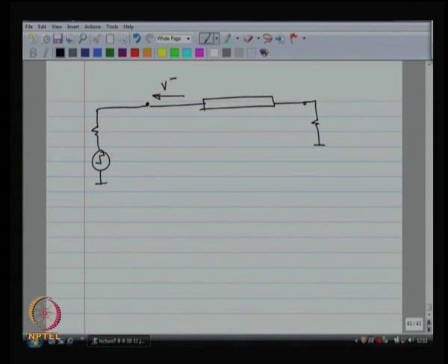Right. When I hit the source with V minus, V plus is already there, right. V plus was the result of the voltage source. When I applied the voltage source at first, it created a positive moving waveform called V plus. Okay. That voltage is still around.